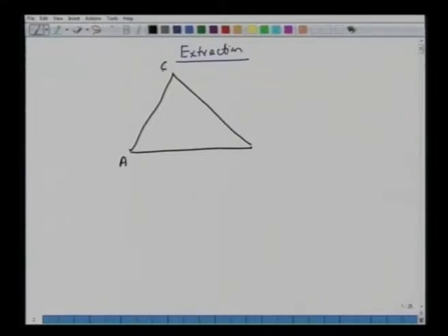Traditionally, we put the solute C here on this apex, and we have A and B here. If you choose any coordinate here, then we are trying to say the amount of C present. C is 100% here, A is 100% here, and B is 100% here. As you go in this direction, the amount of C increases from 0 on this horizontal side AB, and it becomes 100%. If you go here, you can note down the reading on the graph paper, and that reading will correspond to the amount of C.